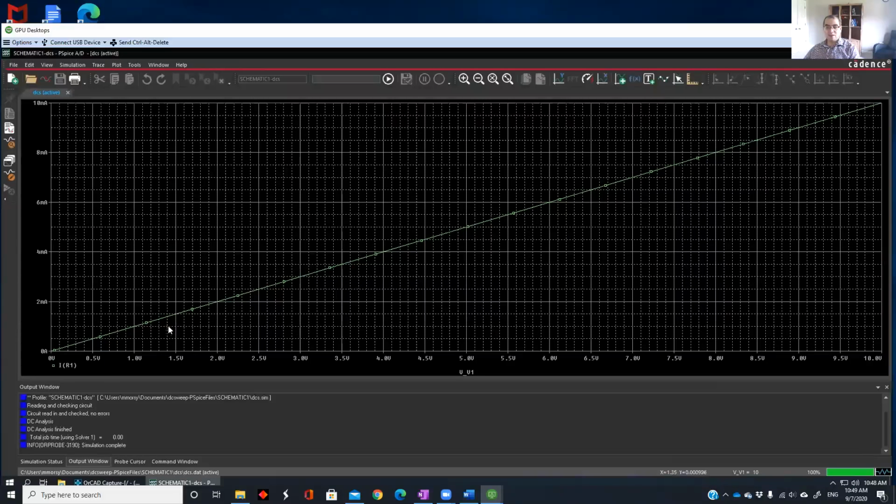All right, what we see now is the voltage and the current versus the voltage. And you can check, our resistor is 1 kilo ohm. So for 10 volt, for example, the current would be 10 over 1K, which is 10 milliamperes. And for 5 volt, it's going to be 5 divided by 1K, so it's going to be 5 milliamps, which is here, and so on.